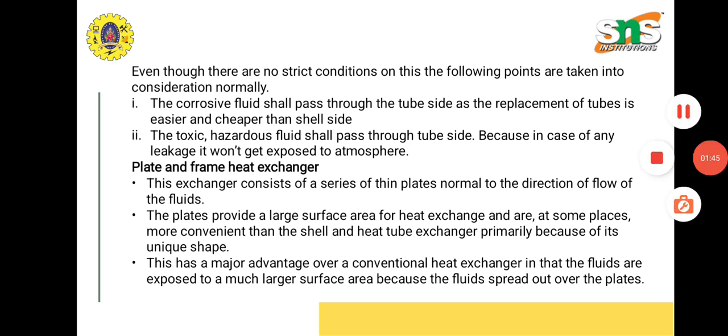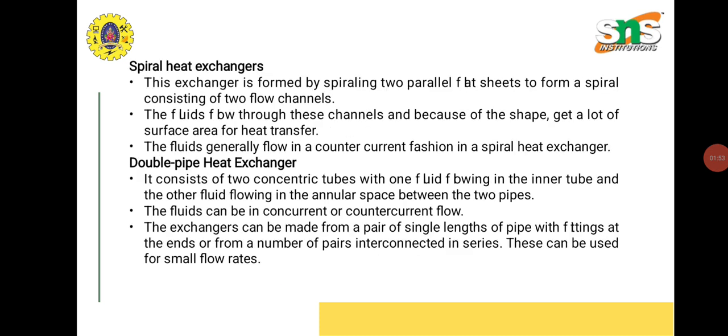Plate and frame heat exchangers. This exchanger consists of a series of thin plates normal to the direction of flow of the fluids. Spiral heat exchanger. This exchanger is formed by spiraling two parallel flat sheets to form a spiral consisting of two flow channels.